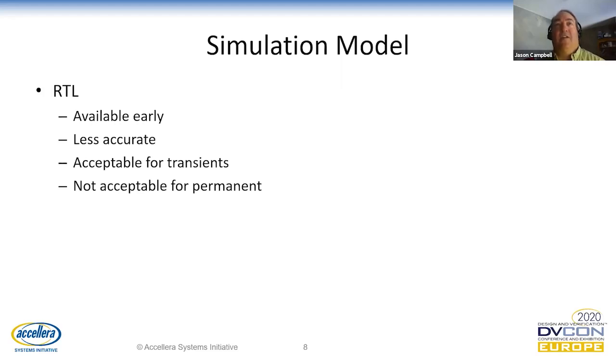The reason is that there's no way to map an RTL fault location into a gate fault location. A single RTL statement may generate 100 gates. So we have no way to map that single statement into 100 gate fault locations.